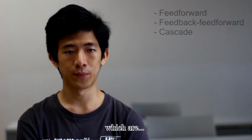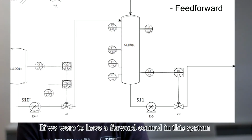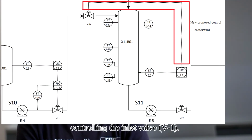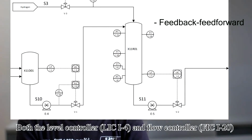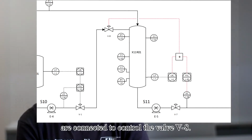To propose a new control system, there are three types of controls available, which are feed-forward, feedback feed-forward, and cascade control. If we were to have a feed-forward control system, the disturbance variable, the inlet flow rate, has to be controlled by controlling the inlet valve V1. If we were to have a feedback feed-forward control in this system, both the level controller and flow controller are connected to control the valve V8.